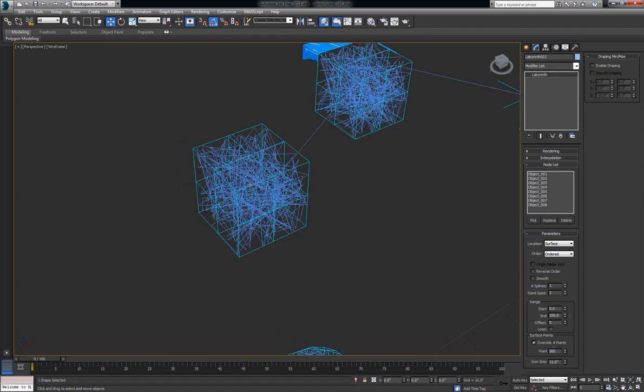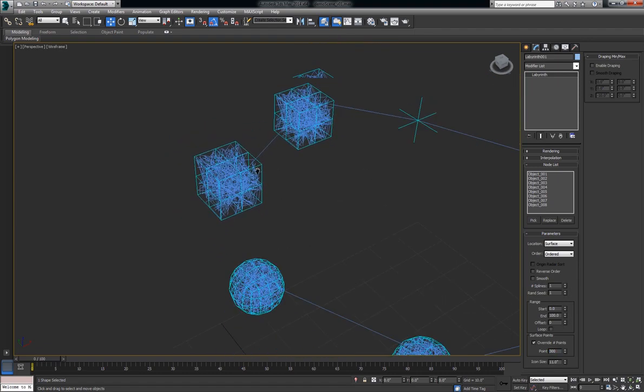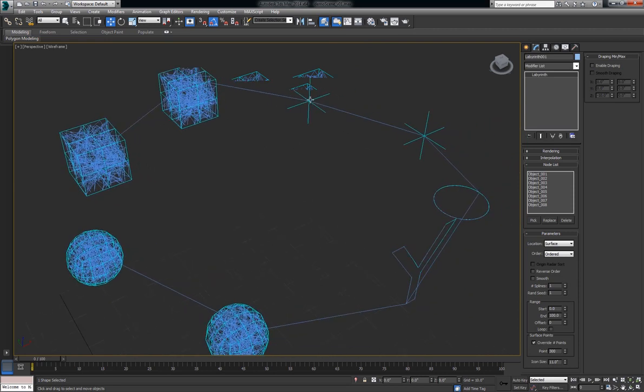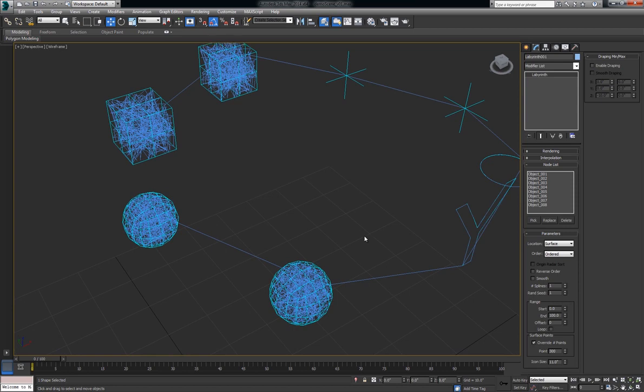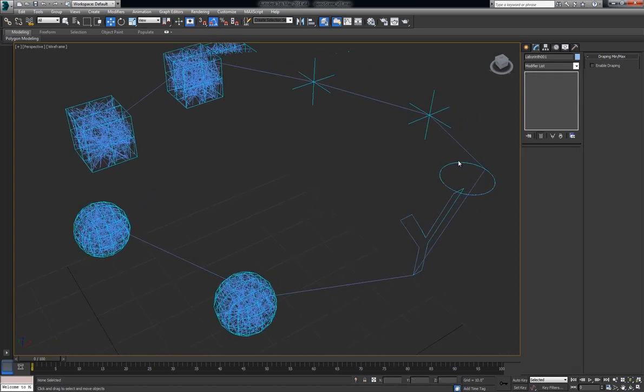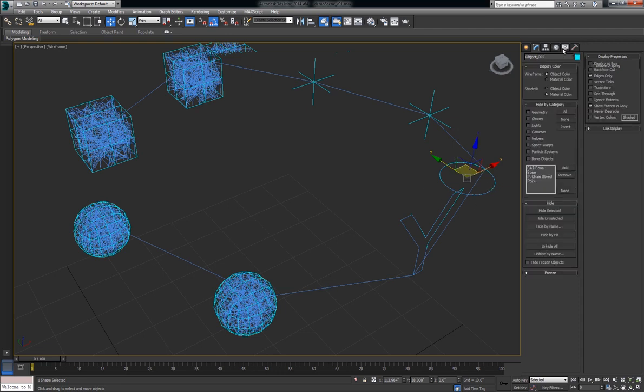And now there's 300 points being generated for each object here you see, and they're probably overlapping a bunch here. And then for spline shapes, it'll divide the spline 300 times and generate points along it. And just to clarify, it doesn't actually modify the object it's being generated on. You'll see the circle still has just the typical 4 points here, and I'll turn that on to show you.